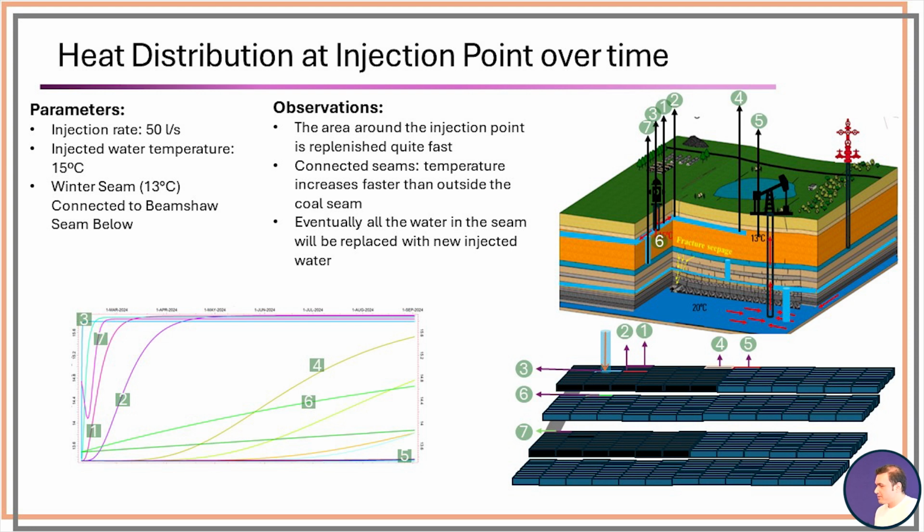Anyway, when you abstract water, usually the replacing water is coming from the same seam or from the top due to gravity, unless there is some specific piezometric pressure at the bottom, which is unlikely in this area. So generally speaking, stay away from connectivities if you want to store heat at some point.